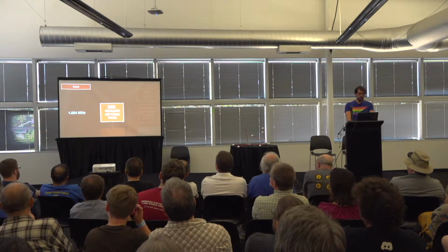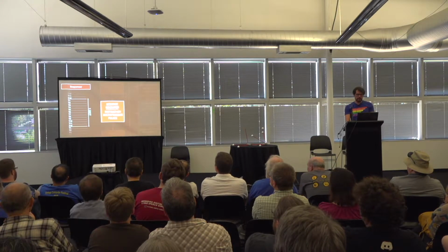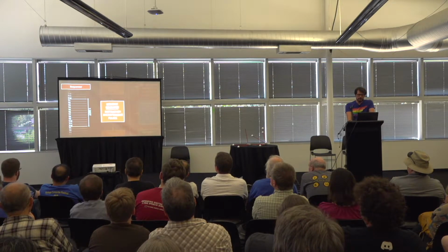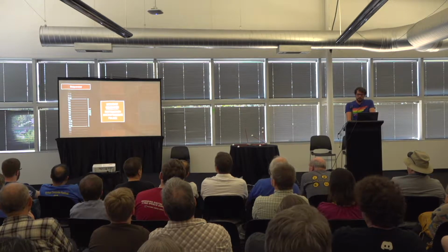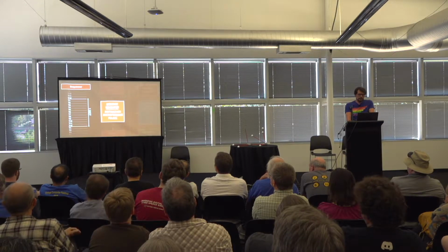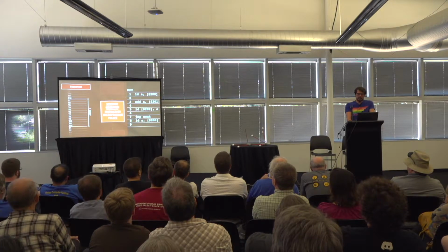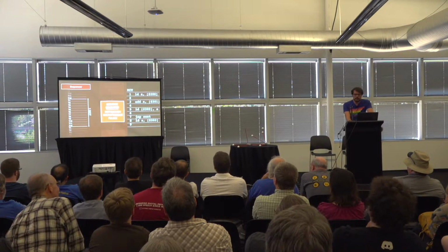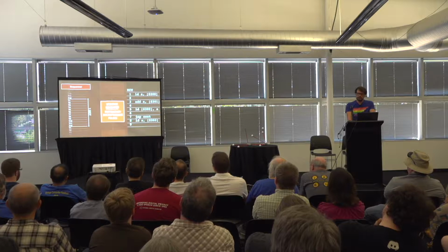The main clock of about 1 megahertz feeds into the sequence generator, which keeps cycling through 12 stages, which is one memory cycle, MCT, memory cycle time. Instructions usually take as many memory cycles as they need memory accesses. So load, add, and store take 2 cycles, and jump takes 1.